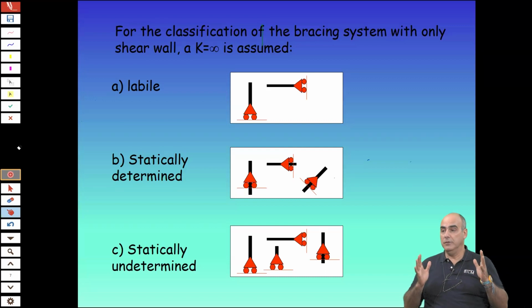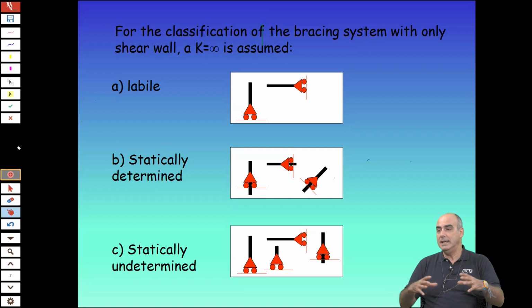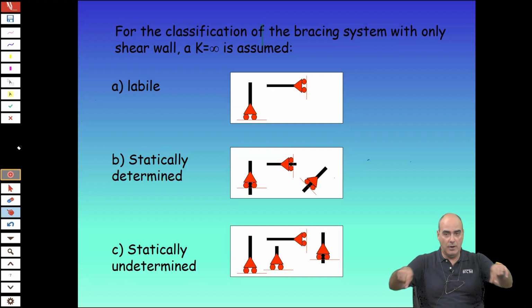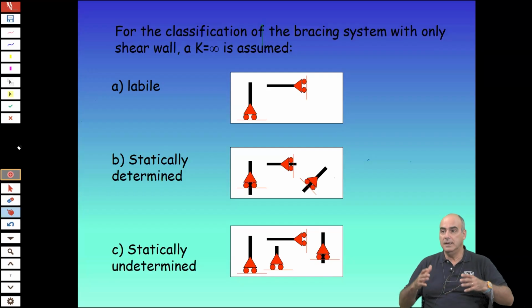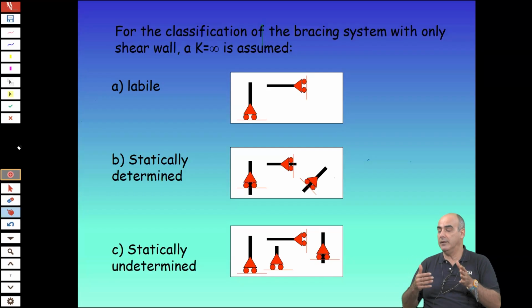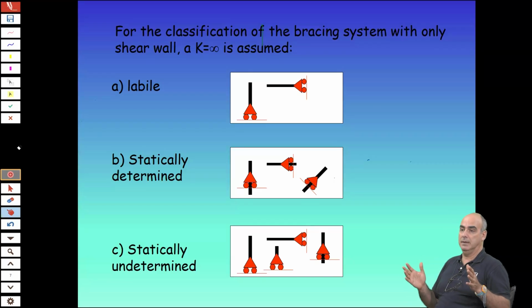First of all, you find written as a principle in design codes that you must provide lateral load resisting capacity. Imagine that your building in plan is a rectangle, or you can put a rectangle circumscribing it. You have to provide a lateral load resisting system along both directions in the plan of the building.